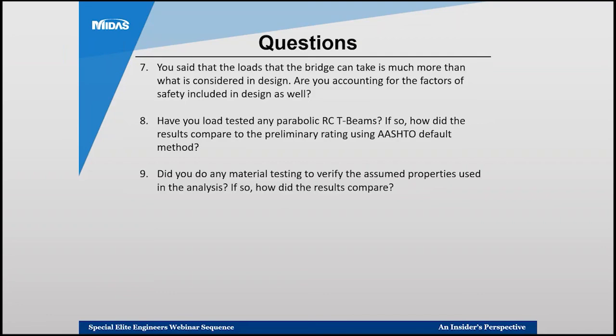But to be specific, for the slab span, the concrete strength has no contribution whatsoever to the flexure strength in general. It's all about reinforcement. So in other words, we did not assess the strength of the slab span. The strength is based on the amount of reinforcement in the slab.